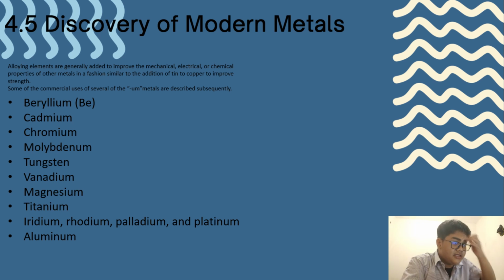Corrosion would severely limit the utility of the steel if chromium was not added. Stainless steels contain up to 30% Cr, and although the primary function of chromium addition is to improve the corrosion or chemical behavior, chromium in small quantities improves the strength of alloy steels.